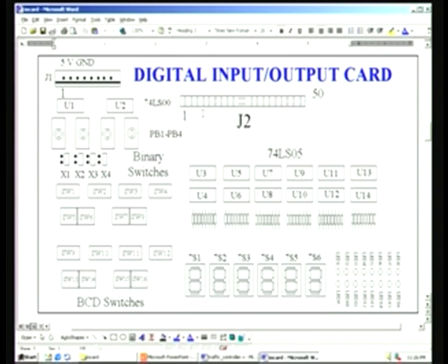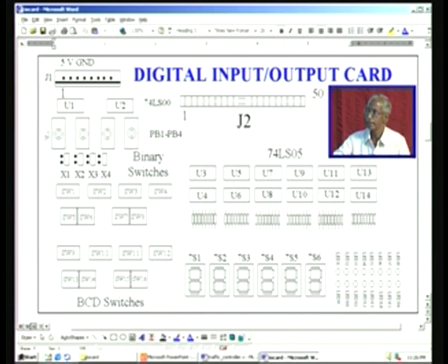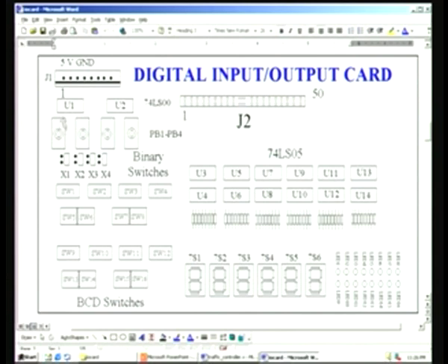And in addition to this, we have push button switches, that is 4 numbers of them, and this is a push button shown here, and you also have some 4 jumpers here, and if you install the jumper on the left, right now it is shown as right install jumper. On the left, if you install, it will automatically select this push button switch, and it is debounced by using 74LS00, and you need cross coupled NAND gates, which we will be covering later on, and out comes the debounced digital value, which is connected to pin number 3 here.